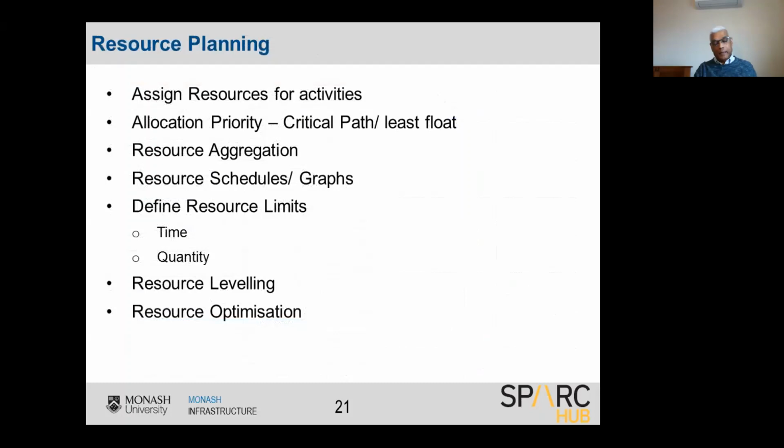And then the next aspect is resource planning. Once you put down the schedule, activity by activity, using the work breakdown structures, then you assign the resources for each task. Say it is a construction activity, a foundation work: how many excavators are needed, how many laborers are needed, so you resource it. That is called resource planning.